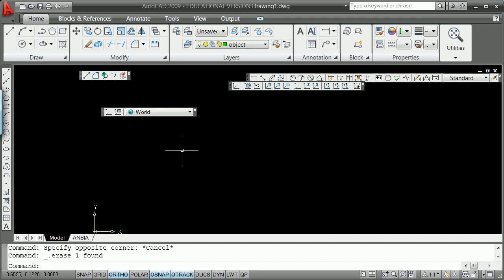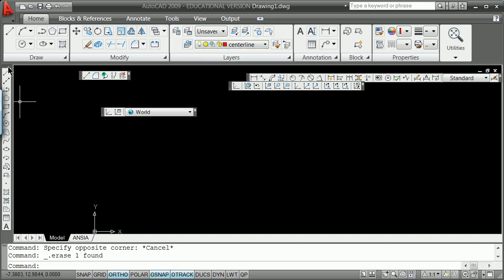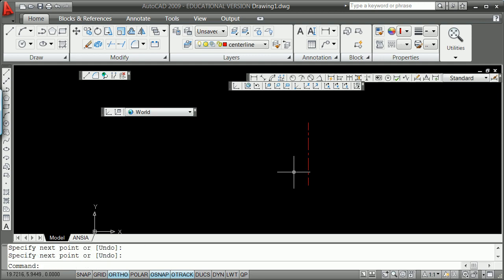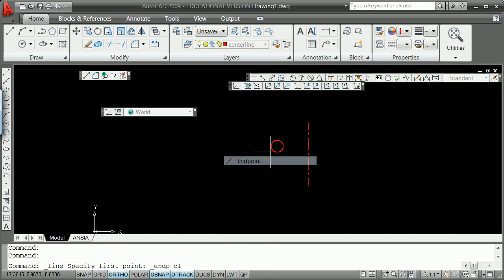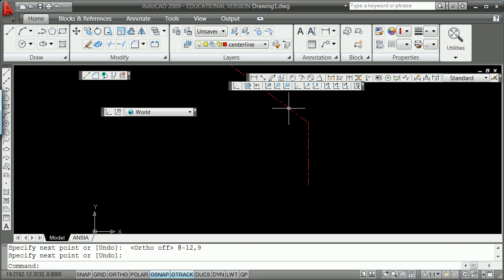Doesn't like that. Okay. I'm going to draft the structure. One of them was straight down. Got my F8 on. That's my force straight down. One of them was 9 over 12, and so I can do that by having a line here from the endpoint, turning off my ortho if I want, and say at -12, 9. Remember AutoCAD, changing X over changing Y, it is not slope.